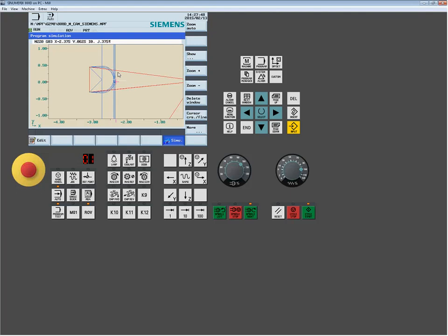So there's our new line on the right, just my compensation. And that's certainly a valid scenario to run your machine, and now you still have adjustability if your parts aren't coming perfectly to size without having to repost the whole file. If you didn't have cutter compensation on and you need to change it because an end mill was undersized or oversized, you would have to repost the entire file and bring it back down to the machine.